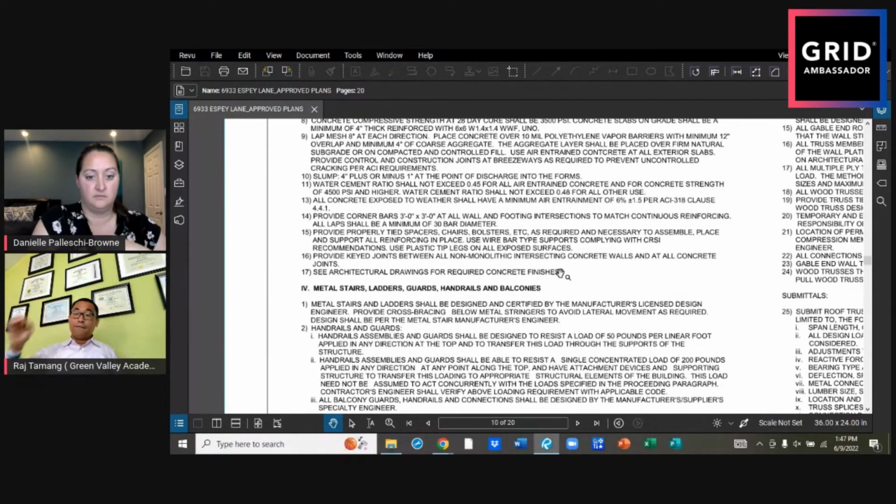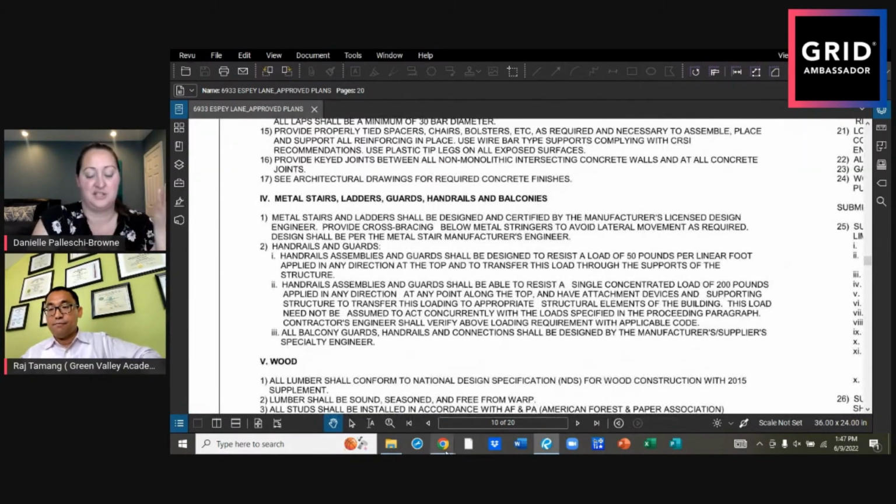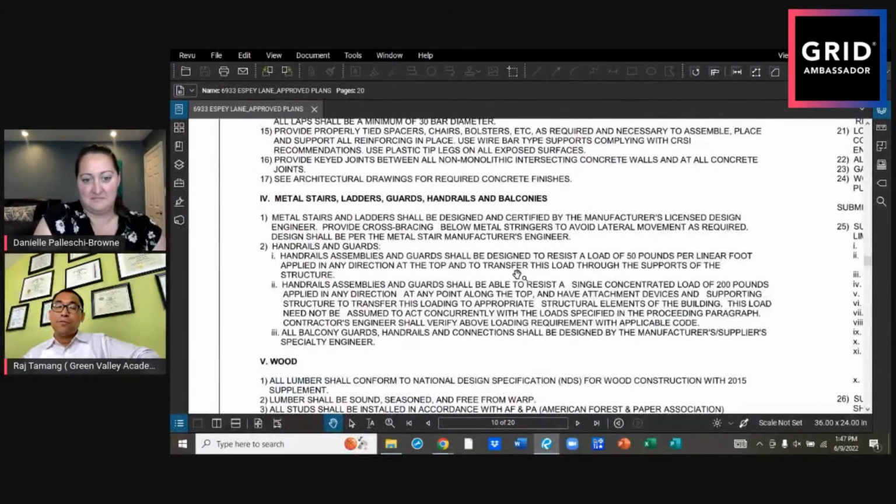That's exposed outside. Very interesting, because I'm getting my patio redone, and it's going to be stamped concrete. So is that going to be air entrained concrete? If you are pouring concrete there, yes. But if you're getting concrete blocks from somewhere, no. But if you are pouring concrete there and making a stamped pattern, yes. Make sure it's not the same concrete. And the guys doing this should know it.